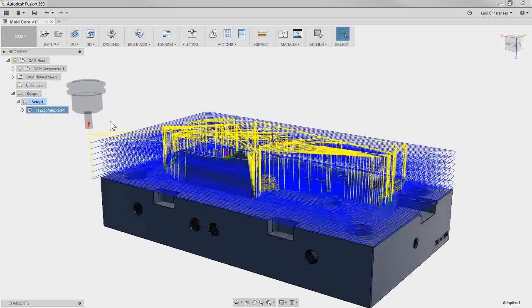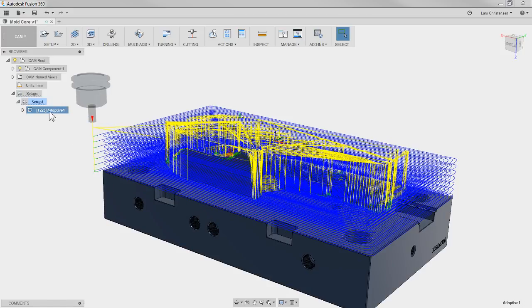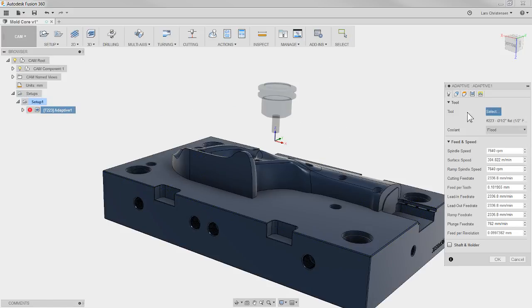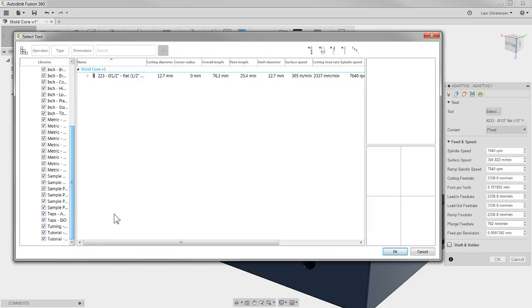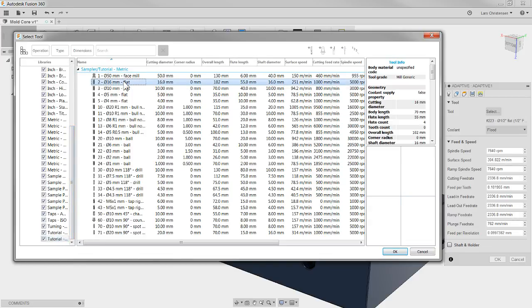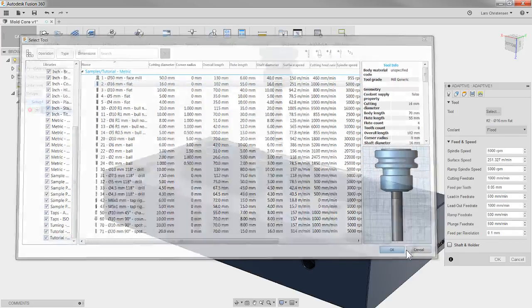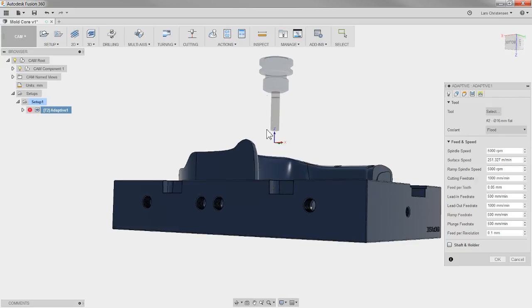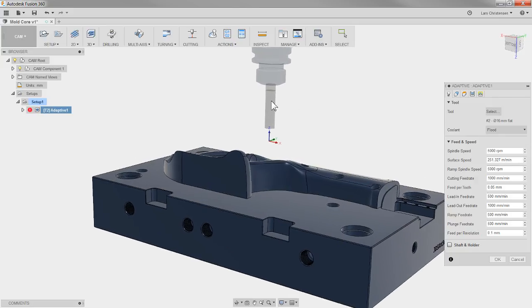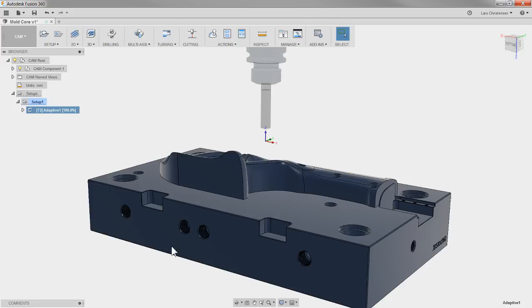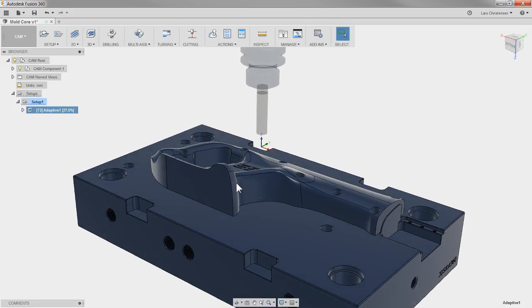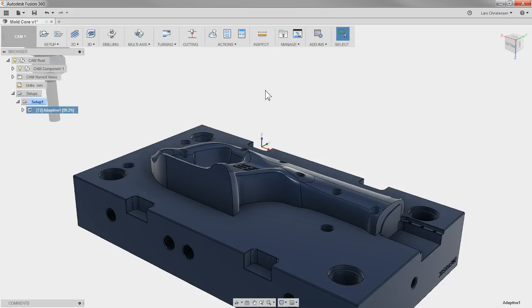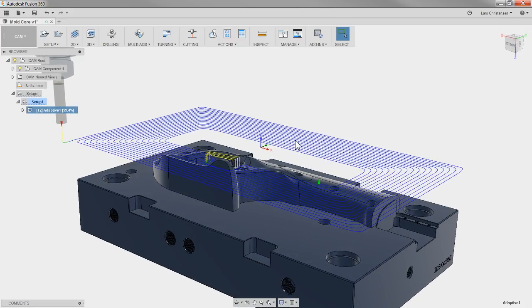Because using that long end mill, let's just switch to that one. The first one in the tutorial library here, I mean, that's a long cutter. Now, that might be good to clean up some stuff, but to rough all this material out, that thing will be rattling and chattering, and that wouldn't be a great solution.